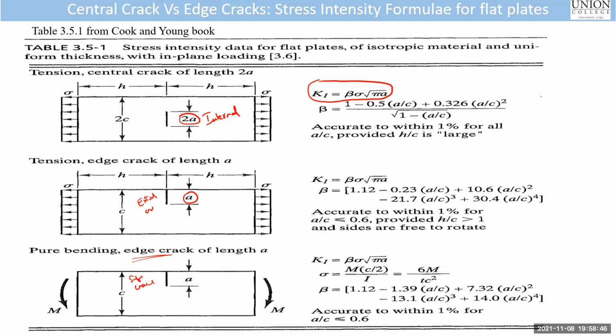If you have an external crack, and because of the tensile loading, you have an external crack and you have a moment. What does moment do? Why are we talking about moment when we're talking about mode 1 here? All of these formulas, you're talking about K1 here, which is the stress intensity factor. Stress intensity is how much the sigma is getting amplified. Even for the bending type of moment, I'm talking about K1. Anyone? Why am I talking about K1 here for bending?